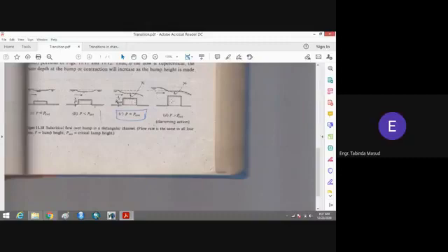Now what happens in case number D? You can see that the height of the hump is increased beyond the critical height of the hump. So what will happen when you further increase the height of the hump? There will be no change in the critical depth of the flow. The critical depth cannot be further reduced.